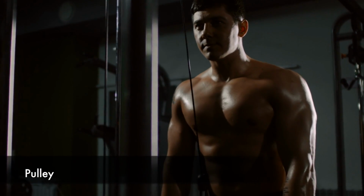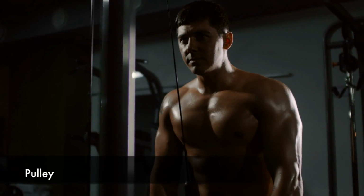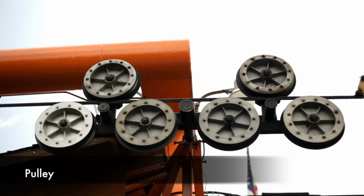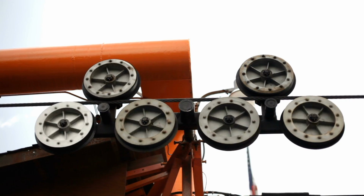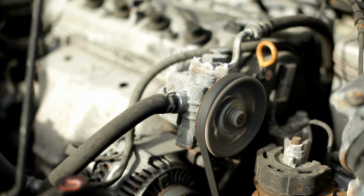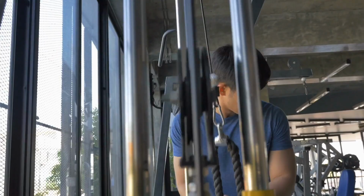A pulley is a wheel that carries a flexible rope, cord, cable, chain, or belt on its rim. Pulleys are used singly or in combination to transmit energy and motion. Pulleys with grooved rims are called sheaves. In belt drive, pulleys are affixed to shafts with their axes, and the power is transmitted between the shafts by means of endless belts running over the pulleys.